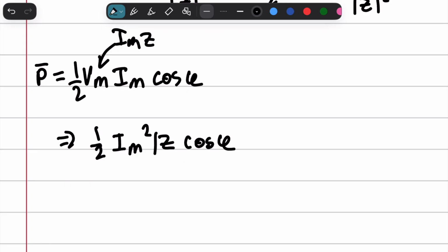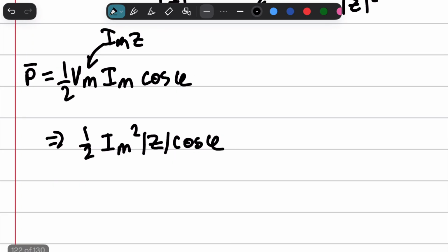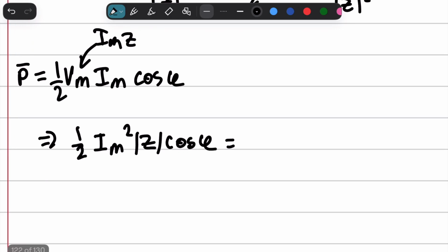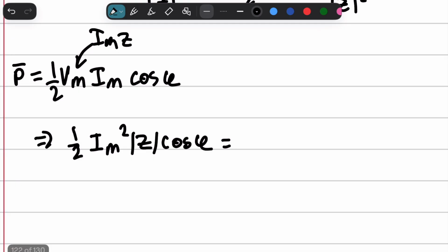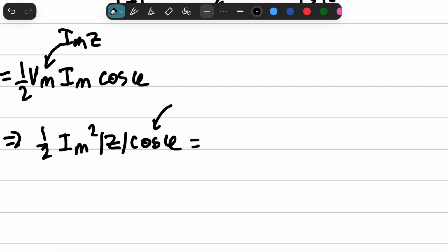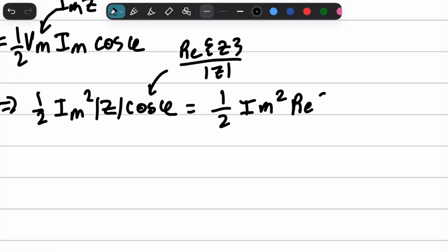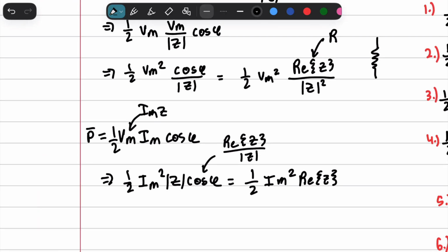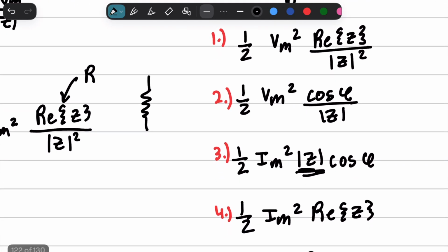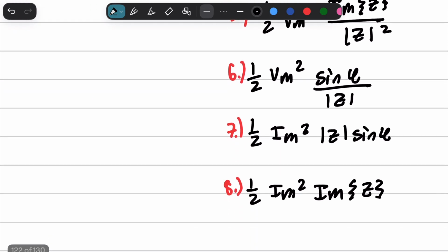And I've put the absolute value bars right there. And once again, we can get our ratio right here. And so the ratio is just the real part of Z over the magnitude of Z. And once again, we plug it in, and we just get this. Okay? Simple. So that's the first four equations, and Q is exactly the same thing.